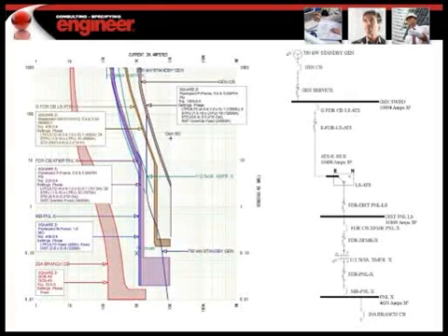As we move forward and look at our emergency side of the circuit, consider when the circuit is served from the single generator. This set of curves demonstrates that our circuit is selectively coordinated when served with the generator. The generator itself produces a lot less fault current than the utility does.